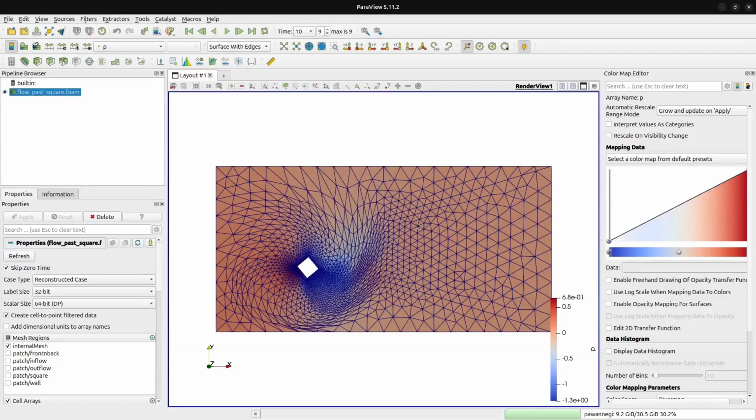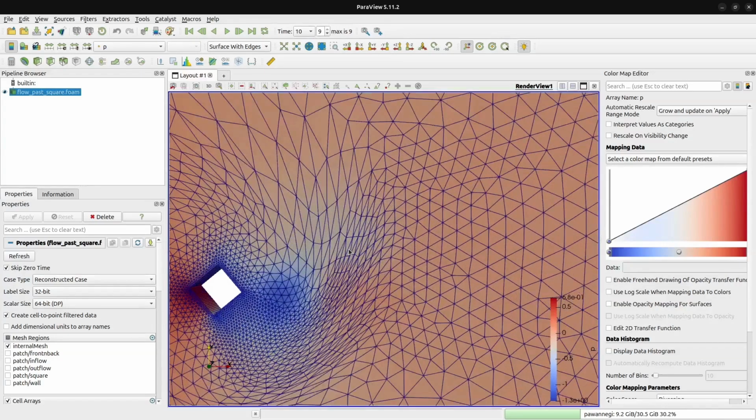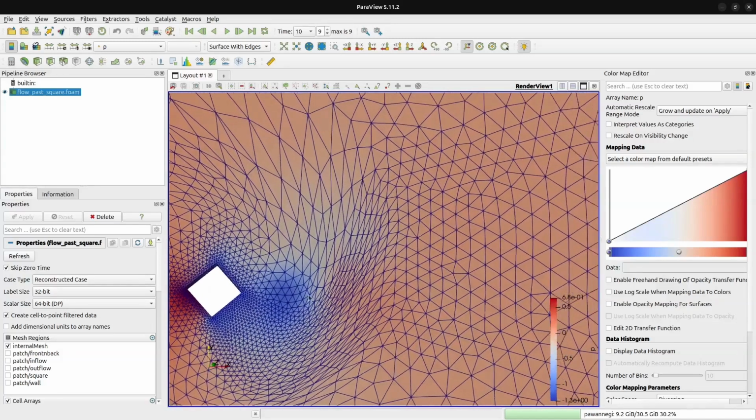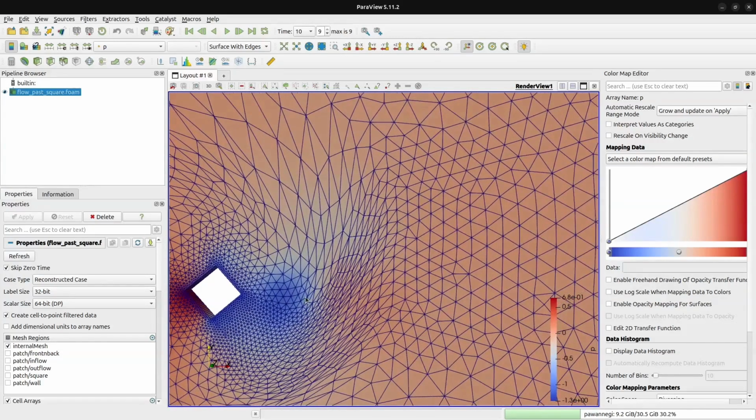This kind of mesh motion does not create new mesh points. It just uses the points and keeps on moving them until it can solve. This is not the best way to solve this kind of problem. There are different kinds of mesh motion that should be used for different kinds of simulation. If there is only a very small amount of motion, then you should use this kind of mesh motion to accommodate that motion into your simulation.